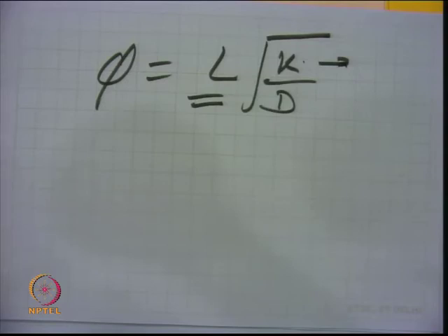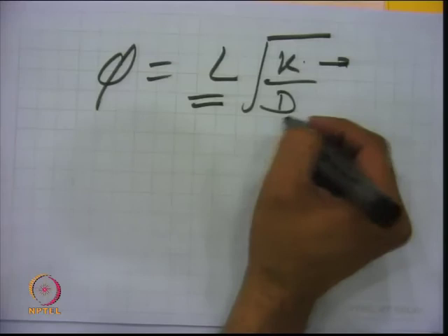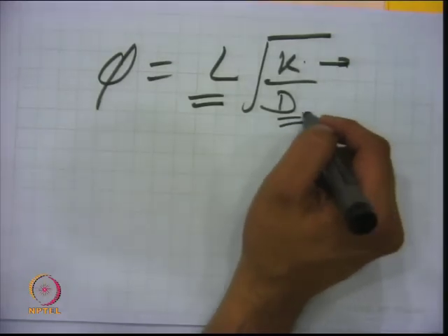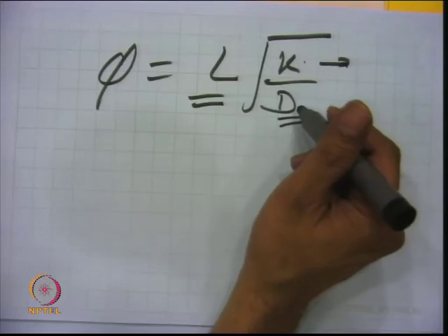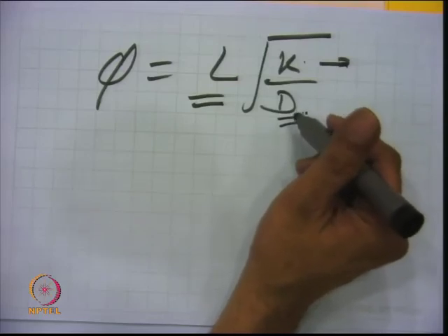Kinetic control study should generally be done at a relatively lower temperature. Otherwise, if the temperature is very high, then it may be possible that diffusion may be governing the rate. And diffusion is a design of the pellet, you have to design the pellet accordingly to make the diffusion coefficient high, with wider pores, or a defined pore structure.